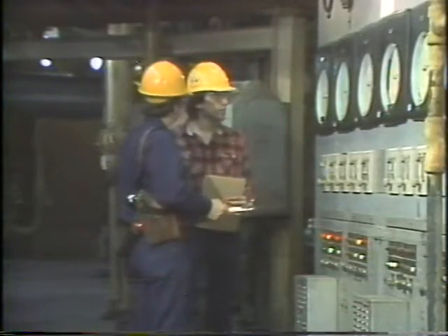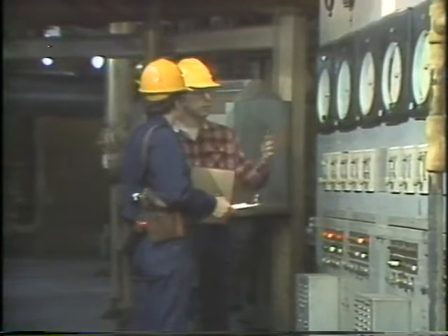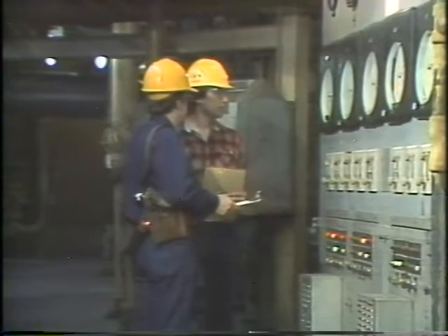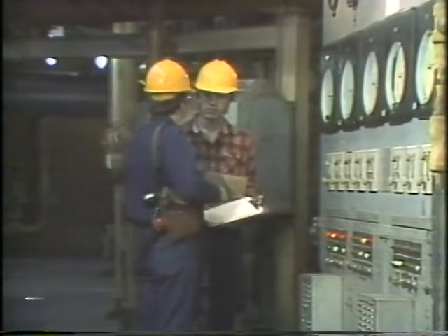The operator said he'd sent somebody up to blow down and check the sight glass on the drum. And the level in the drum was a little high, which agreed with the indication on the recorder. Now, this told Bob that probably both the drum level transmitter and the recorder were working properly. Then Bob and the operator looked at the indicators on the control panel so that Bob could see the indications for himself.